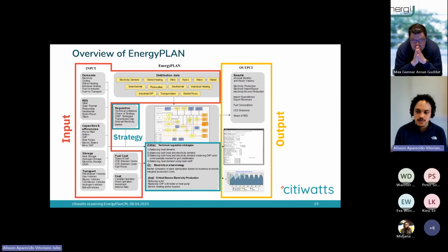These inputs are based on libraries, which are to illustrate the scenario behavior, and they are on an hourly definition, which accounts even for the leap years, which means 8,784 data points. And then the outputs can be retrieved based on a strategic simulation approach, which can be determined inside the graphical user interface of EnergyPlan.